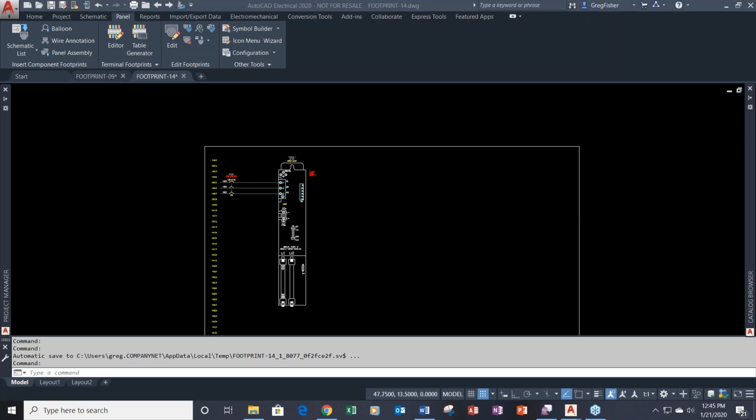Does the database have to necessarily be used, or can you use the user-defined list of objects? You can use that to insert them, absolutely, but they still ultimately have to be linked to a part number. What is a wildcard? Wildcard is simply, you're having multiple part numbers linked to one footprint symbol.